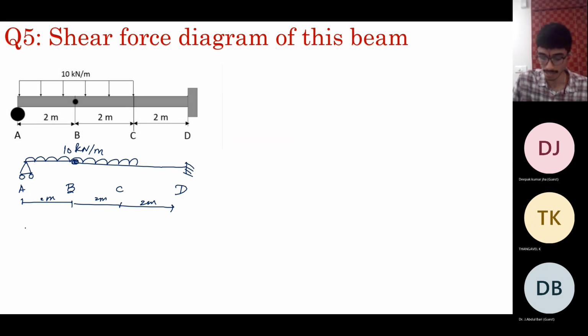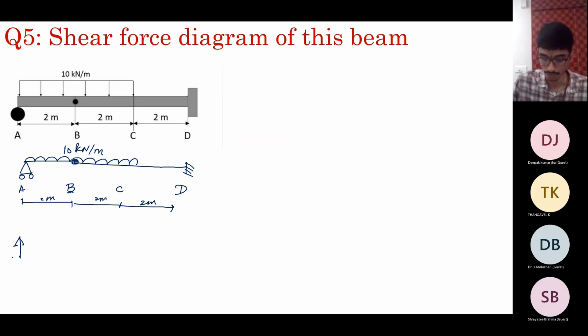Now, as usual, the first step is to isolate. So replace this with the vertical force. Again, horizontal forces are 0 because it's a beam. You have AY. There's no moment. It is a hinged support. Here you have By, and Bx is 0 because it's a beam.